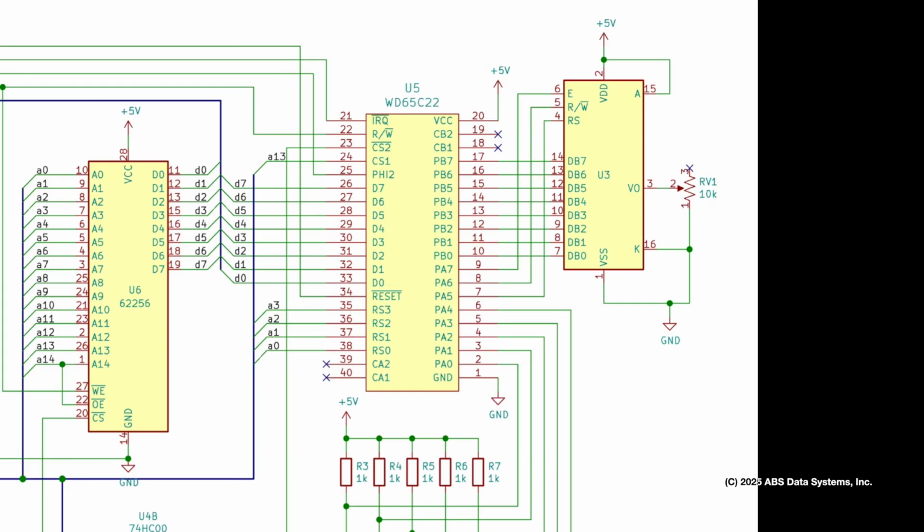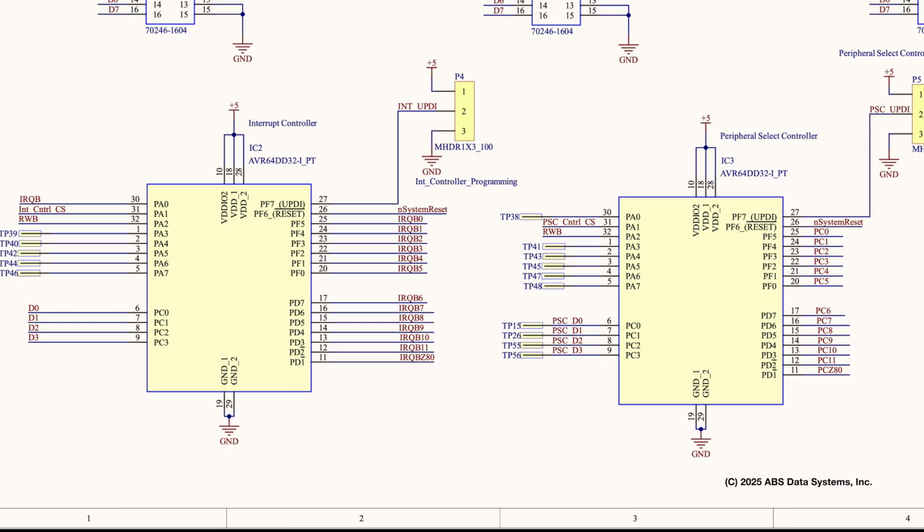I know other designs use a PIA, Peripheral Interface Adapter for I/O. This is where the PIA acts as a middleman between devices. The PIA I looked at seemed very slow and limited. There are a lot of steps to read, and it's only 1 byte at a time. In my design, I'm using a couple of AVR chips to replace the PIA controller. Since each board is connected to the bus, has their own processor, and includes a buffer, I feel that the old PIA concept and associated bottleneck would not work well with my design.